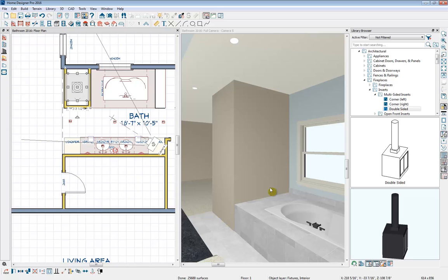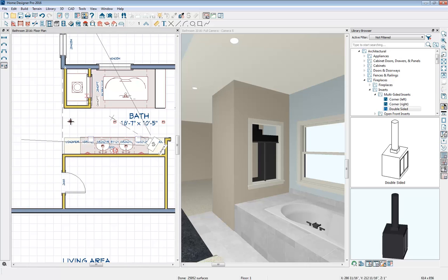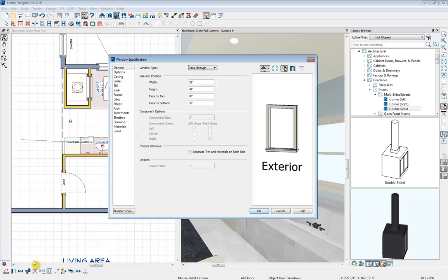And select OK. So now that's floating within our walls. Let's get into our window tool, select that pass through, and then just single click and drop in a pass through. From here, I'll open up that pass through, change the dimensions. We'll do 40 inches wide and maybe 36 high. And then let's bring that up to maybe 30.